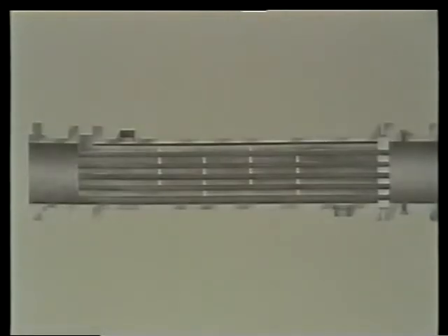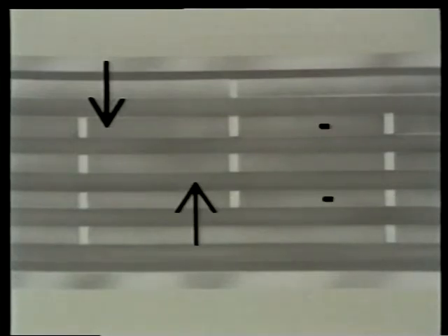Some compressors are also equipped with aftercoolers. Air discharged from the compressor passes through a bundle of tubes surrounded by a flow of water. The water removes heat from the air before the air enters the receiver. Those are the two solutions used to reduce the heat of compressed air: air cooling and water cooling. Either kind of system will reduce heat buildup.